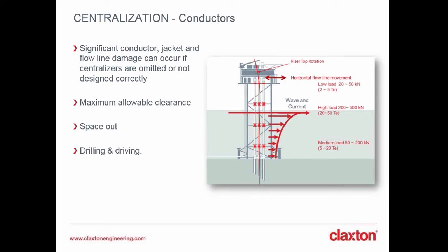Even if the centralizers could take the axial loads, you wouldn't know exactly where the section of the conductor where the centralizer was installed will end up relative to the guide. So that's the reason why they're retrofitted.